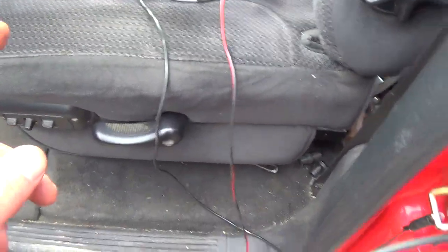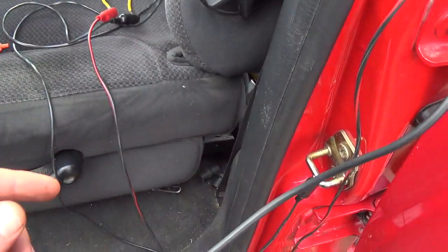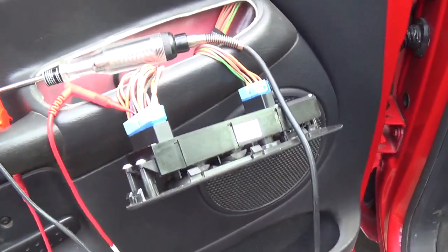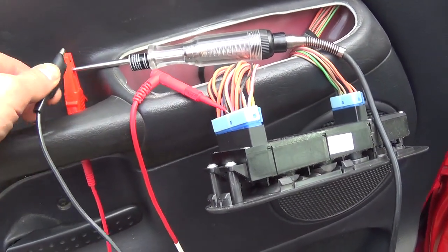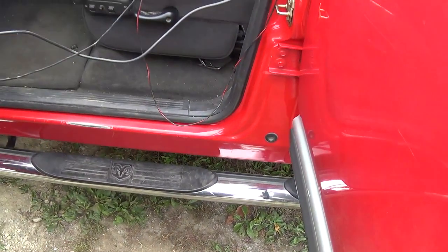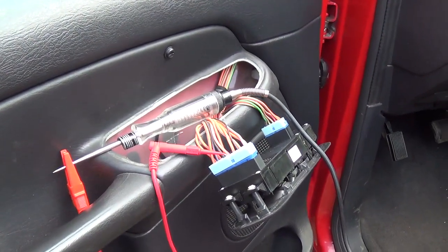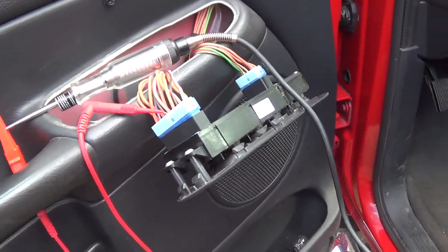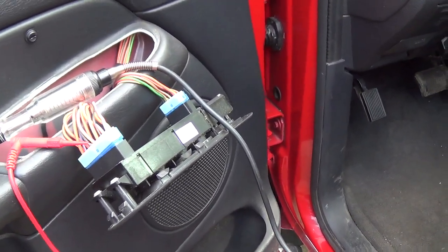So basically, now what I'm going to do to lift that window back up, we're going to put this. Ready for some sparks? That one wire we're going to make constantly positive now. Alright, what will that do? Lift our window. So that's confirmed. We can even, well, I mean that's it. So broken wire, and this door will work.